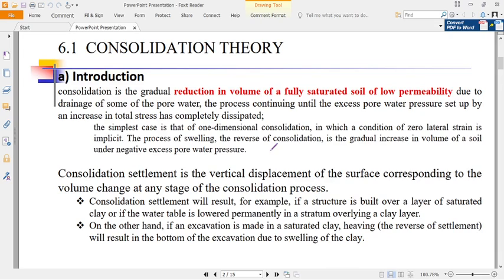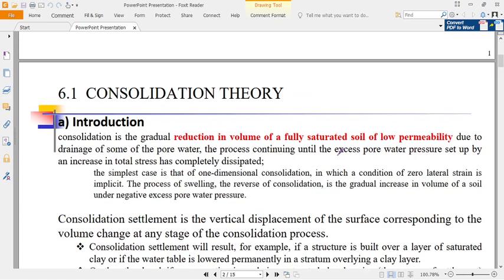So we have seen that from our chapter 1, we found that one of the soils which you have to deal with is the swelling soil, clay soil. And so we say that this soil has a tendency that when it's saturated, when you apply a load on it, it has a tendency to change its volume under loading, through either expansion when you remove the loading, or under compression, as a compressible soil, when the pore water is dissipated under application of an excessive loading.